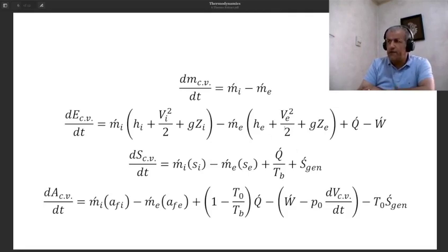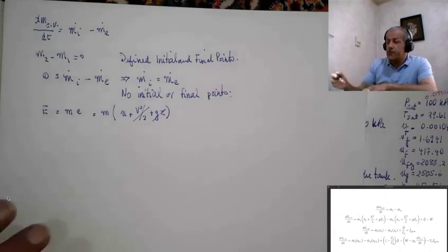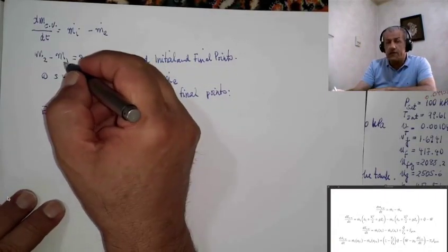So we have now simplified this equation. There is no work, there is no inlet mass, there is no exit mass, and therefore the change of energy between cases 1 and 2 would be a function of heat transfer and work. The work is not there, so it's only heat transfer. You see here again, just like what we did with the mass conservation law, we could do it here as well with the first law of thermodynamics.